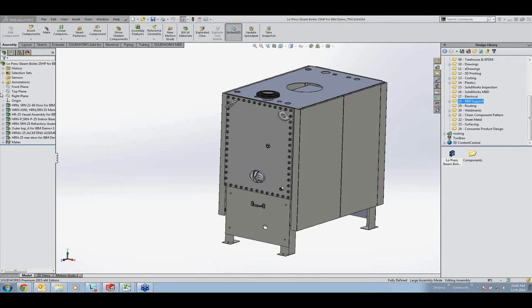Once it loads. There we go. There are now additional tools when creating a surface fill command. Surface fill is the name of the feature here. I can now show curvature combs and zebra stripes while I'm doing the surface fill. Instead of creating the surface fill, then looking at the curvature combs or zebra stripes, now I can do this while I'm creating the feature.